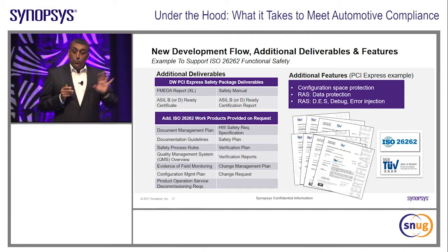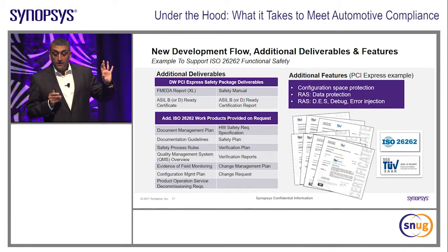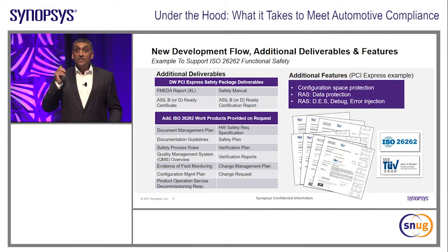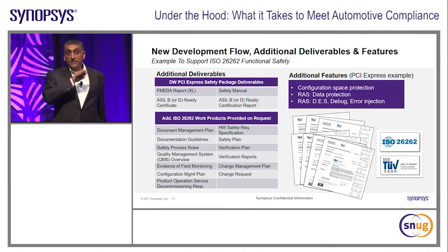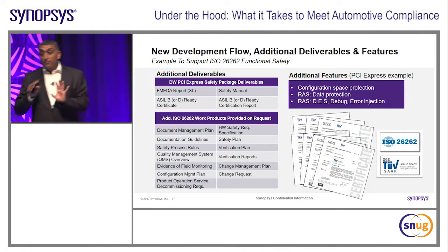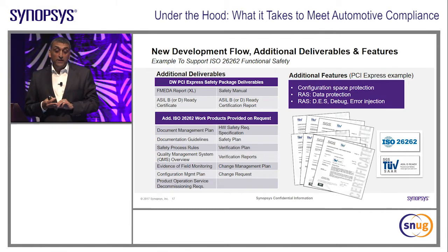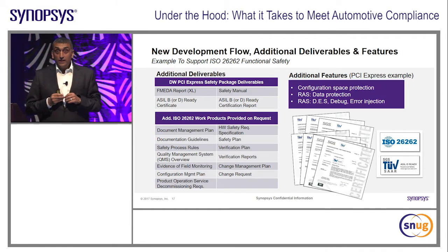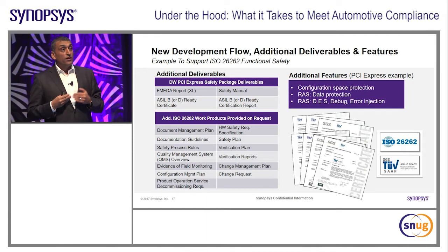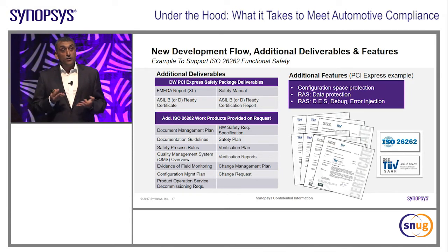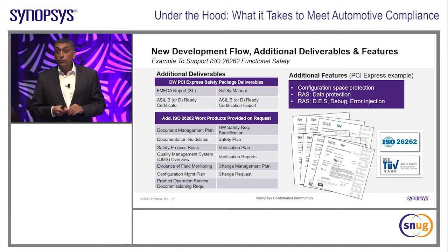If you couple that with the functionally safe controller, that whole system becomes safe because all the CRC type checking for RAS can be done in the digital IP block, thereby not necessitating making the same changes to the hard IP. So there are trade-offs. You need to make sure that this is agreed upon with all the auditing and management of the systems, but you can make some trade-offs in the IP development in order to support the functional safety requirements. So it's onerous, but it's not so onerous.